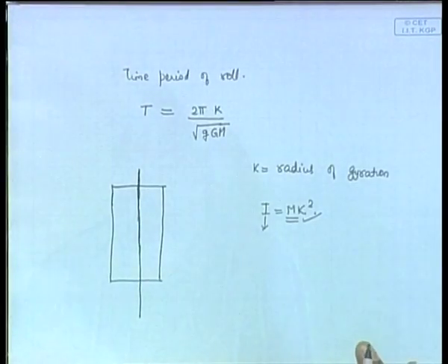From our definitions and derivations of stability so far, I have said many times that GM should be as large as possible, right. I said that the minimum condition is that GM should be greater than 0. The more you have, the more stable it becomes. Okay. That is the general principle. Now, you might think the best thing is obviously to keep on increasing GM by some way. For example, you can move weights to the bottom, all the weights you keep pushing to the bottom of the ship, and the top part remains relatively empty, and you will get G at the very bottom. The G of the ship will come down because all the weights are shifted down. If that happens, is that good or bad?